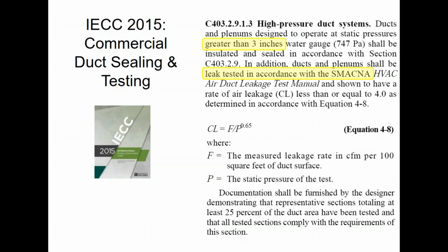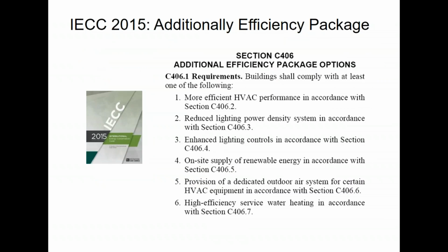So either you have to do that, or you have to look at your design really hard and be like, do I really need 3 inches of static? Can I get it done with 2.6 or something like that? And reevaluate that decision. Otherwise, you're going to have to seal the ducts much better in order to pass one of these leakage tests because they're pretty stringent. So that's part of your rooftop project as well.